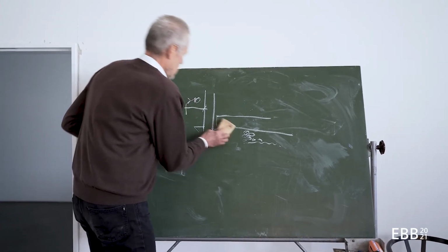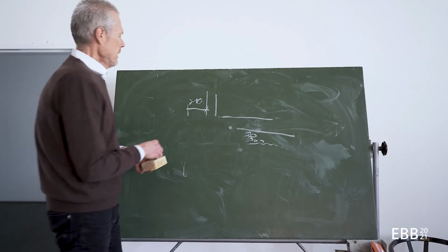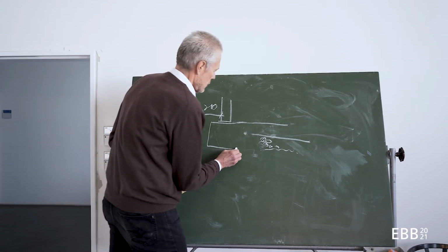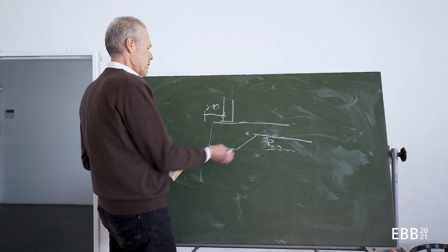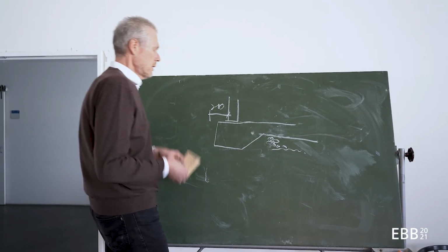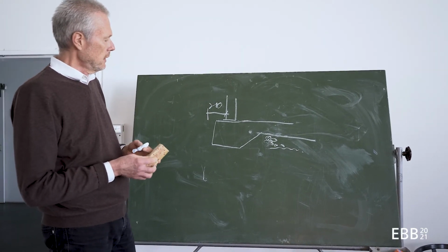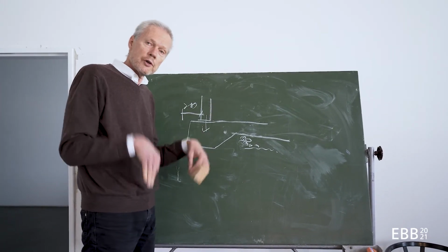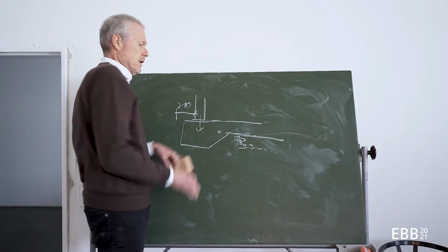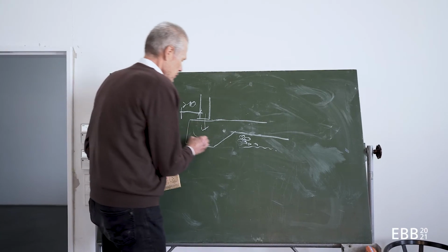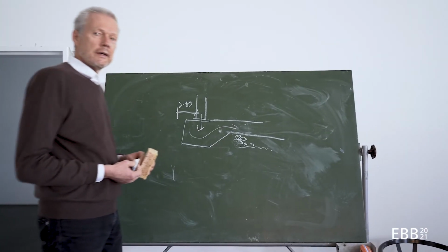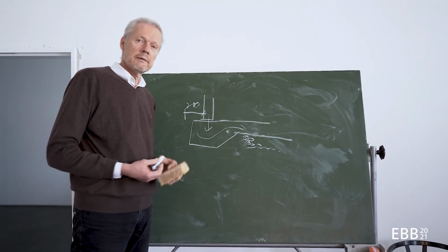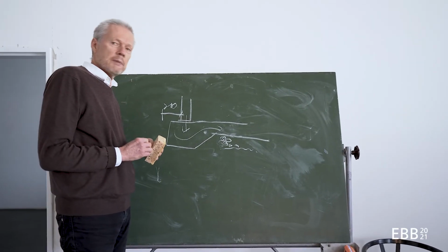Another solution would be to link both of them. So if I'm linking them, I can get up a little, and what is often done for convenience is to create a little slope here in the floor plate, to create a better correspondence to the vertical load that is meeting this floor plate here that rests on the ground, so as to solidify this in a better way. I'm integrating the foundation in the horizontal base plate.